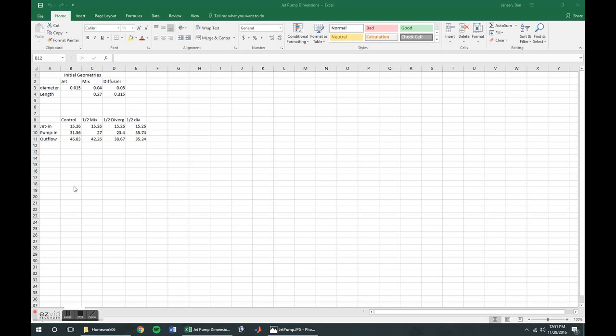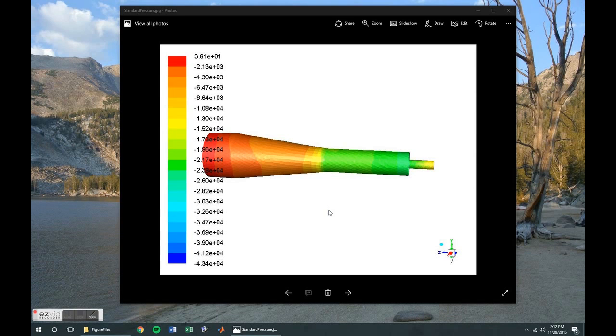As you can see, halving the diameter of the mixing tube had the most overall effect on the flow through the tube. Just some quick speculation about this, I'm guessing it was probably because the smaller diameter is more restrictive, and there are also more influences from the wall friction factors and things like that. Alright, so now we've got a quick wrap-up conclusion here.